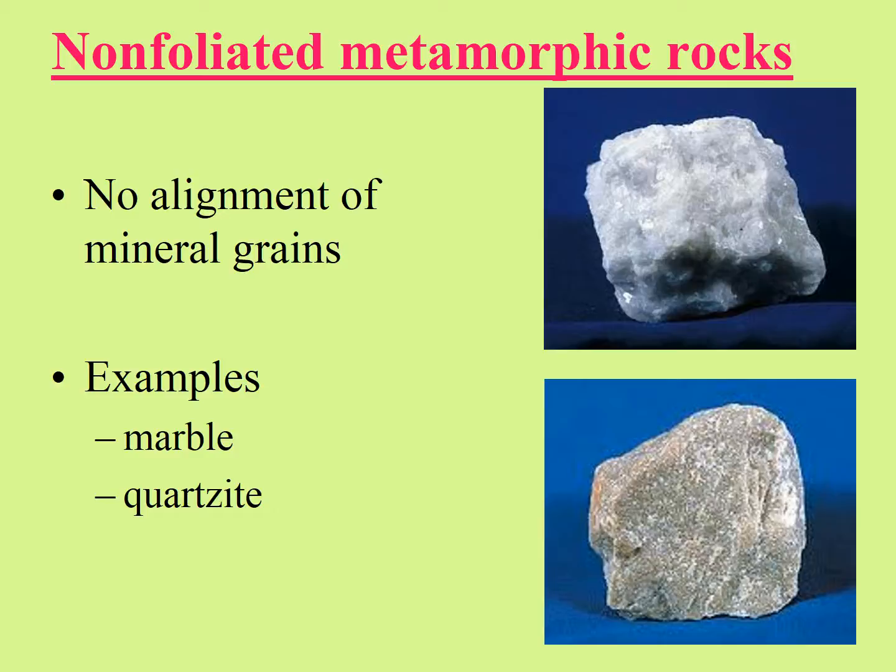Marbles would form as a result of metamorphism of limestone. So marble has the same chemical composition as limestone, calcium carbonate, but it results from the metamorphism of limestone. Notice that I mentioned that marble has the same chemical composition as limestone, and if you'll remember, limestone can dissolve when exposed to acids. That's why when you think about a marble countertop in your kitchen or bath, remember that real marble can be easily attacked by acidic materials, so you wouldn't want to leave lemon juice on top of your countertop if it's made of marble. So when we talk about marble countertops in the home, we're probably not talking about actual marble, but sometimes it is real marble that people use for that purpose, but it's going to be prone to weathering.